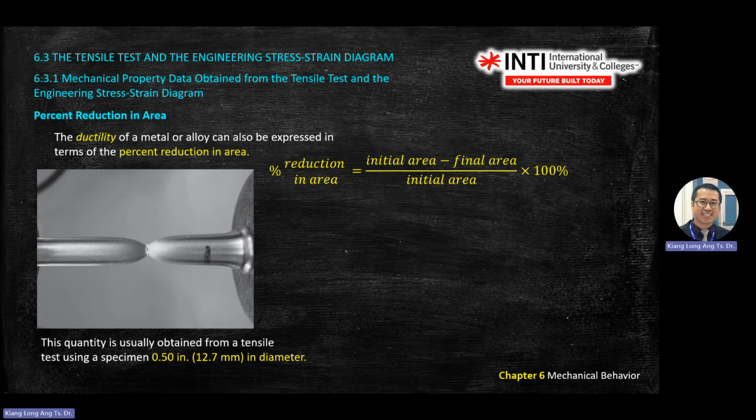Okay, how do you describe the ductility of a metal? You use reduction of area, or strain, actually it's a strain percentage, and we use area. Or if you see the question mentioned ductility already, you need to calculate the area. Just giving you hints: if the question mentions ductility of metal, in your solution we expect to see area calculation.